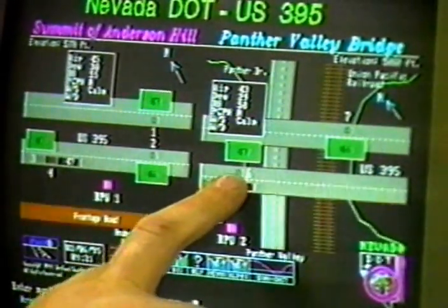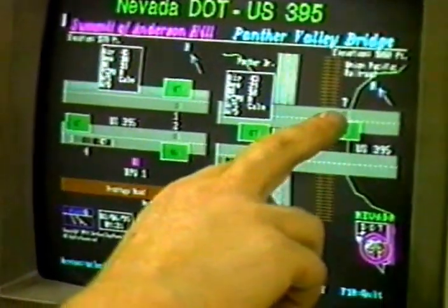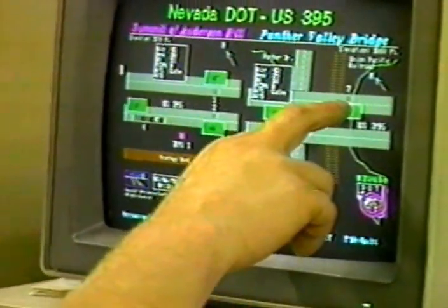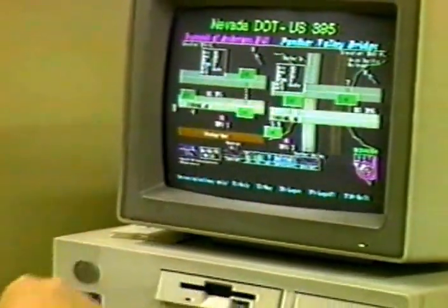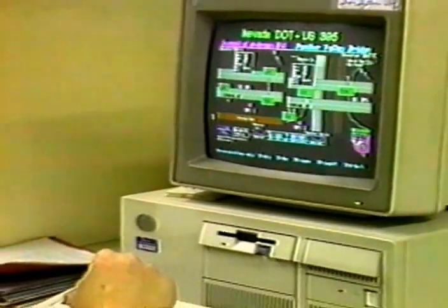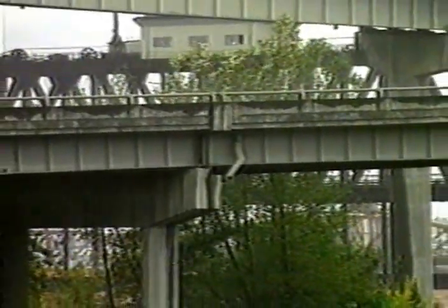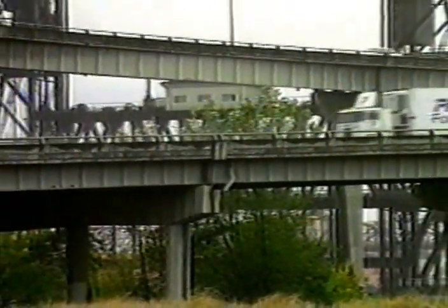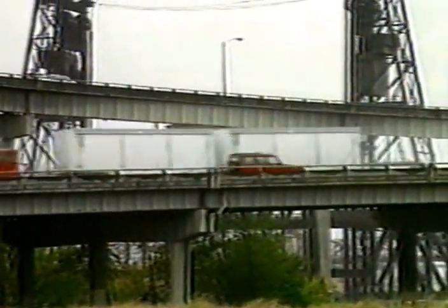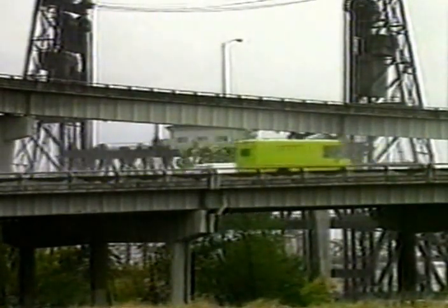Pavement temperature sensors provide real-time data that can be used to predict several hours in advance when the pavement temperature will drop below freezing, allowing time to plan efficient operations. Conductivity sensors indicate the relative chemical concentration on the pavement surface. This helps guide the decision whether to apply more chemical. The newest pavement sensors can measure the freezing point of the chemical solution on the pavement and warn if the solution is likely to freeze.